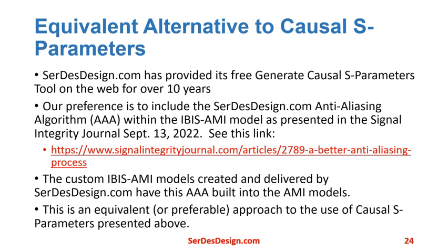See this link for that paper. The custom IBIS-AMI models created and delivered by SerDesDesign.com have this AAA built into the AMI models. This is an equivalent or preferred approach to using the causal S-parameters presented above.